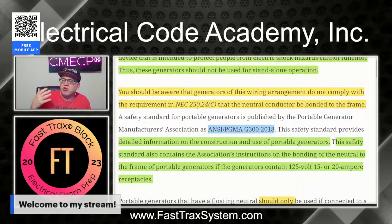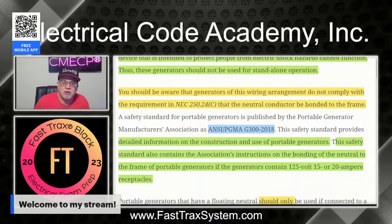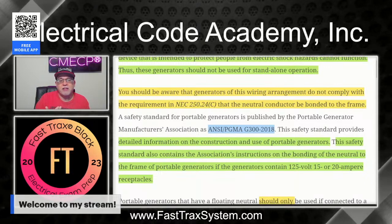if you happen to try to use one of these generators to supply like a dwelling or something like that, then it becomes pretty critical that it can't comply with 250.24(C) if it's a floating neutral because you don't have that neutral to the frame connection. Okay, that's a problem, right? All right, next, is there a safety standard for these generators?